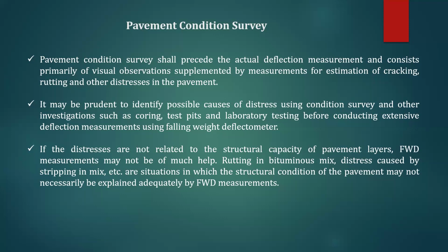In the olden days, when the BBD test was conducted, test pits were conducted even then. A test pit is something like making a pit on the right side or left side of the carriageway. A staggered manner is always better. You need to understand what the different layers are, how much thickness, and what the soil is.